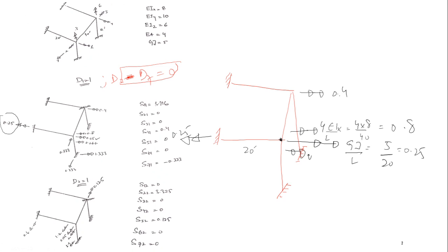This would be equal to 4EI_x/L. That means 4 into EI_x is 8, and the length of the column is 12, so it comes out to be 0.2666, and it would be half. It is 2EI_x/L, or simply 0.133.